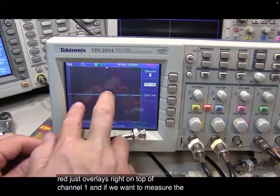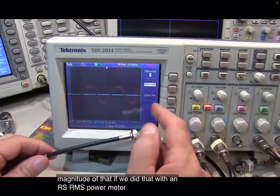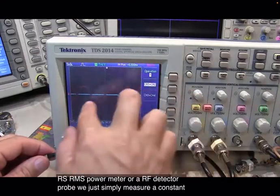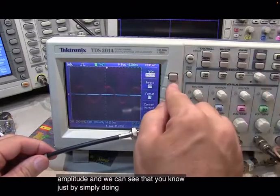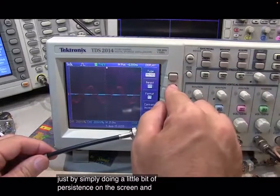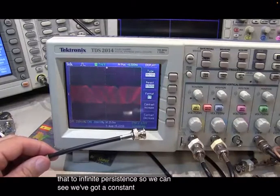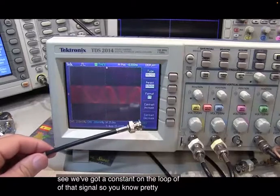If we wanted to measure the magnitude of that with an RMS power meter or an RF detector probe, we'd simply measure a constant amplitude. We can see that by using a little bit of persistence on the screen. Let's set that to infinite persistence, so we can see we've got a constant envelope of that signal. So pretty easy to understand.